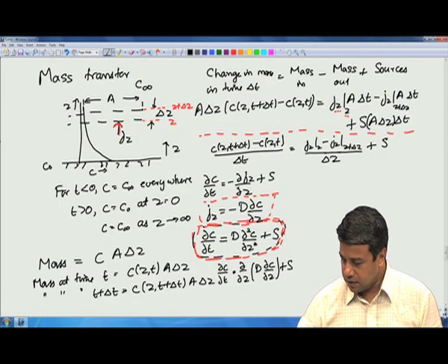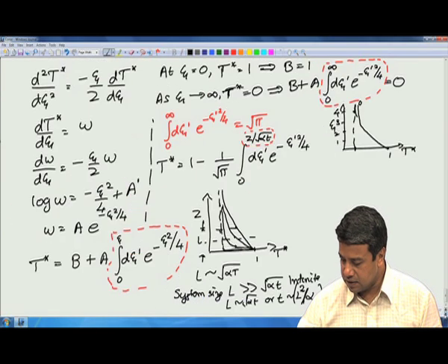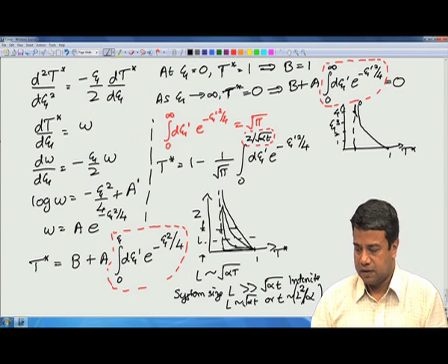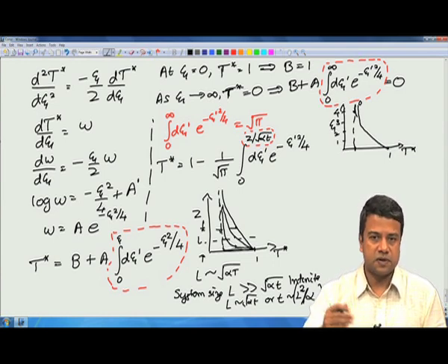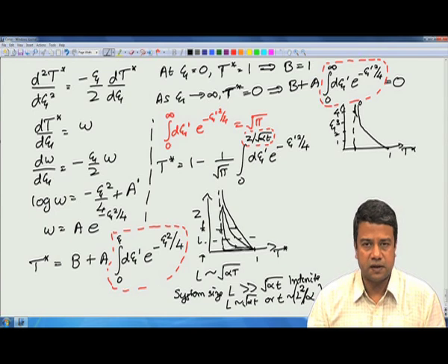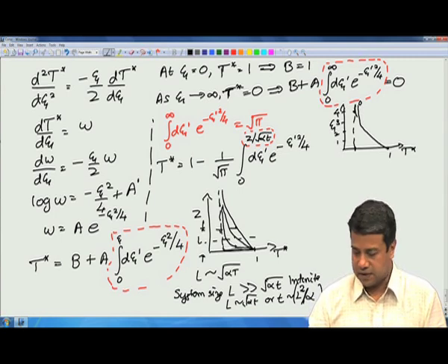Good. So, now we have looked at under what conditions this approximation is valid. Obviously, this approximation is valid so long as the time of heating is small compared to the thermal diffusion time across the height of the container. Once it becomes comparable, you no longer can assume that the fluid is infinite. So, next thing, how do we calculate the fluxes in this case, for example?